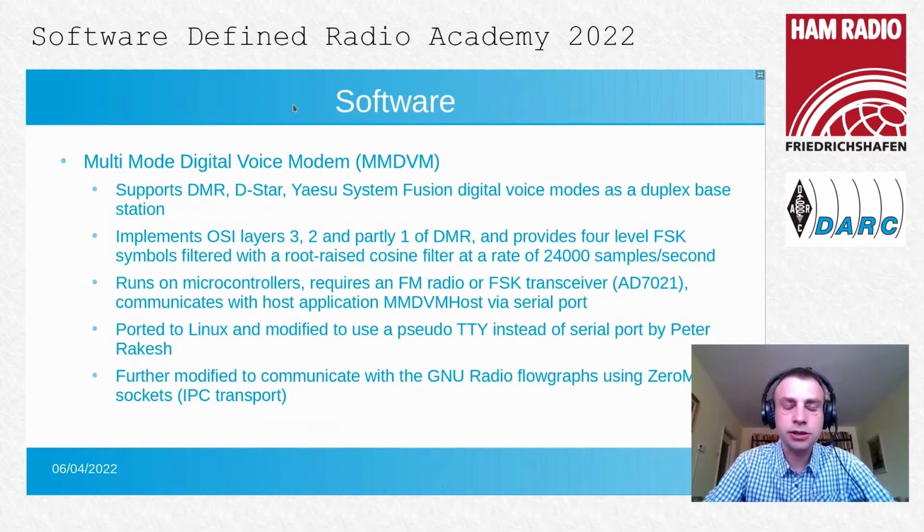The most important one is, of course, the multimode digital voice modem, or MMDVM, created by Jonathan Naylor. This application, which is actually comprised of two separate components, MMDVM host and MMDVM itself, supports DMR, D-Star, and Yaesu System Fusion digital voice standards, and can create a duplex base station. So essentially, somewhat like a normal repeater station.